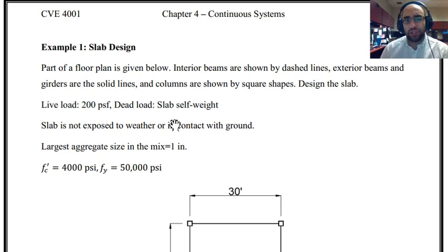If you look at the project, that is very similar to real buildings, and as you can see, for the majority of the dead load that we have on the floor, we have the slab weight or the load per area just for the slab. Of course, over there I estimated the slab thickness, and based on that I came up with the dead load, but once we design the slab, we will see that that will be the governing parameter in terms of the dead loads that we have on the slab.